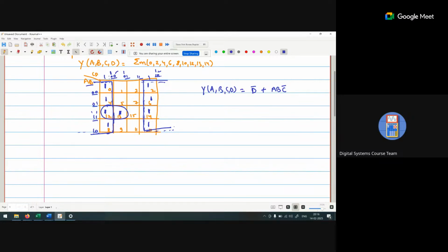Okay, what is the Gray code? Gray code is a one unit distance code. So basically if I write 00, 01, 10 and 11, in this particular part 2 bits are changed. So to overcome this problem, we convert this code into the Gray code. Gray code is 00, 01, 11 and 10. So now between every corresponding value only 1 bit differs, so the distance is unit distance. Okay, so it is called the unit distance code.